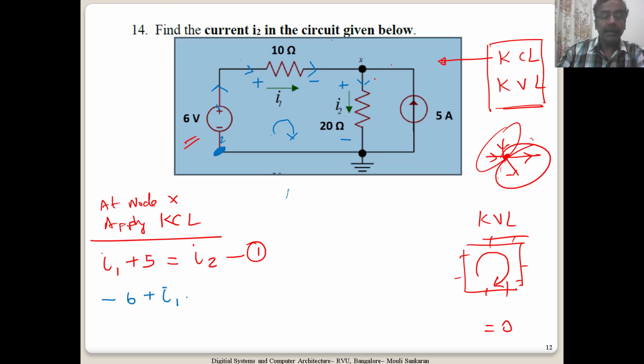10 ohms, I1 into 10 ohms, I1 plus 10, okay. And then I am showing the current I2 flowing into the R2, the 20 ohms resistor. So the current is entering its positive terminal, so I am encountering a positive here. Don't go into this loop, okay. This is just feeding the current. So you have to complete this one loop which is here, okay.